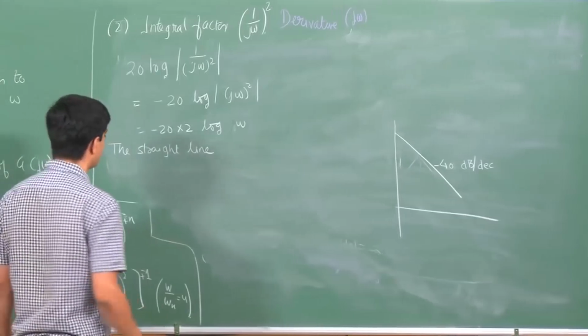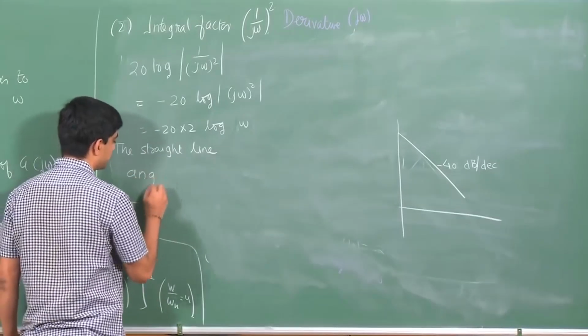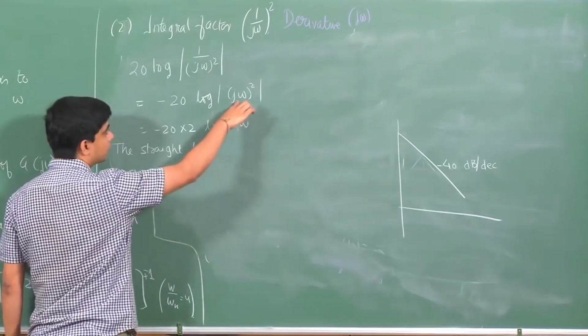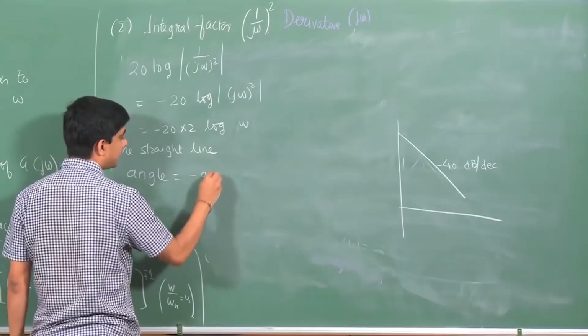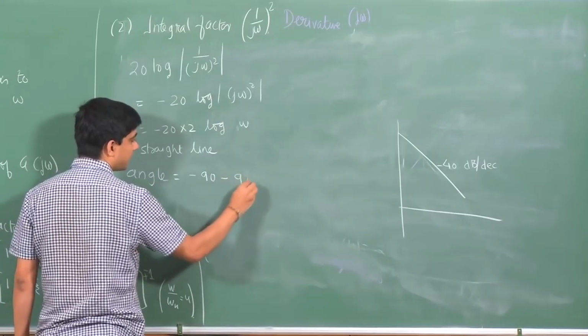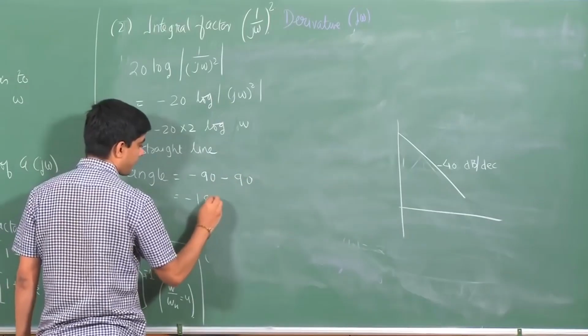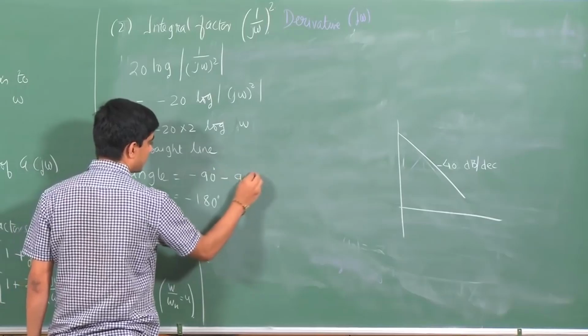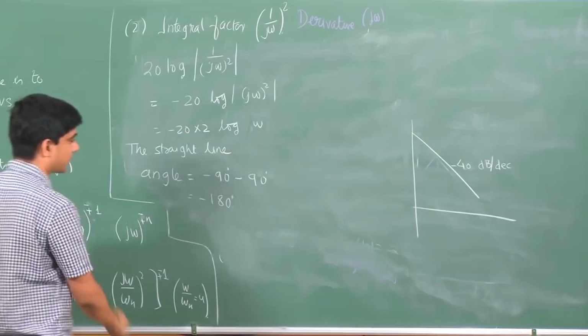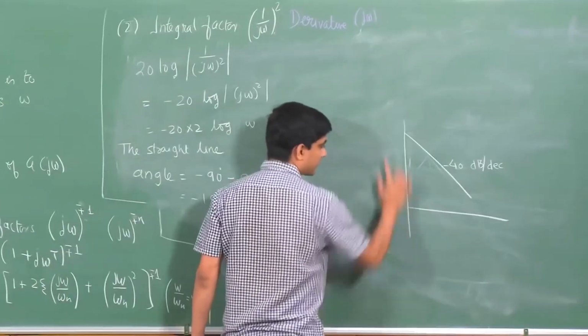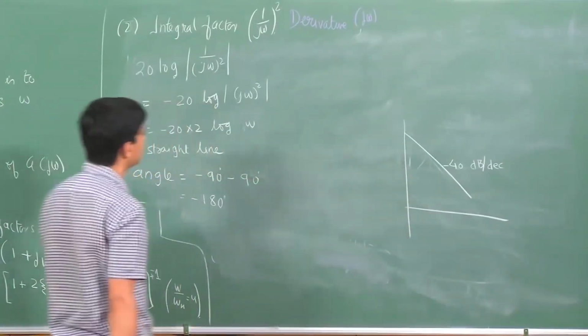Okay, and what will be the phase? Phase, well, this is phase of 1 over j omega is minus 90. I have another of the same guy. This will be minus 180 degrees, all in degrees. Okay, just straightforward. I will not really now draw this scale and what is this and all. That is kind of now easy to compute.